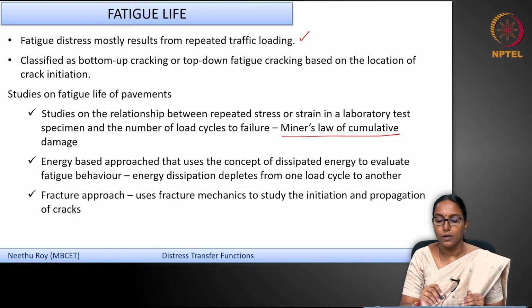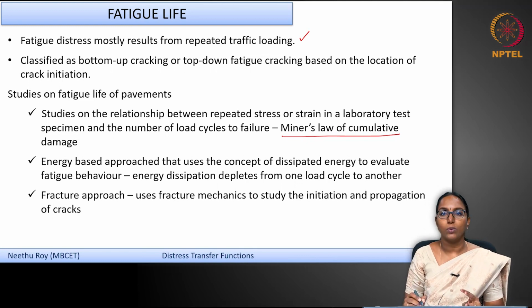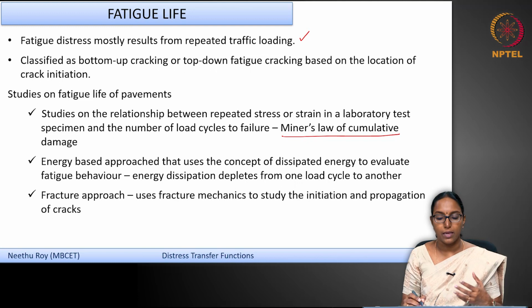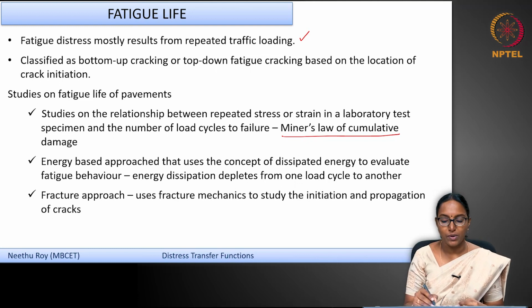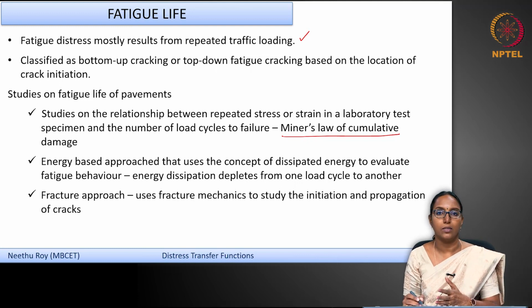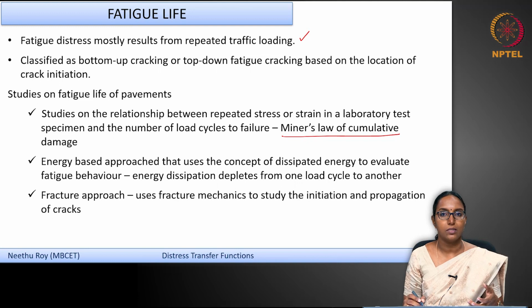So, this approach is called Miner's law, and the second one is the energy dissipation approach, wherein what you try to find out is how the energy gets dissipated at every load cycle. It is found that the energy dissipation actually depletes from one cycle to another. So, based on the energy dissipation in this specimen, you can measure how the fatigue life of this material is going to progress.